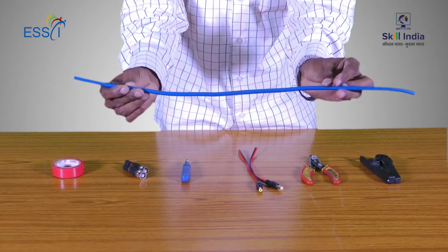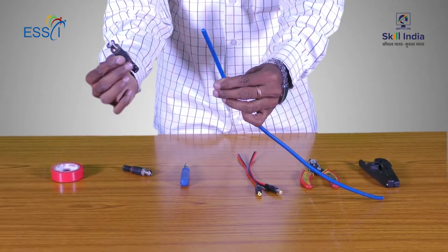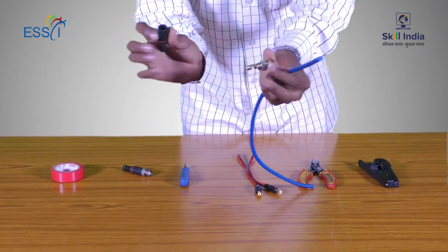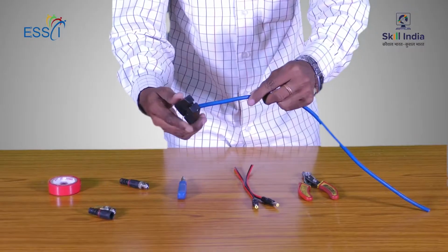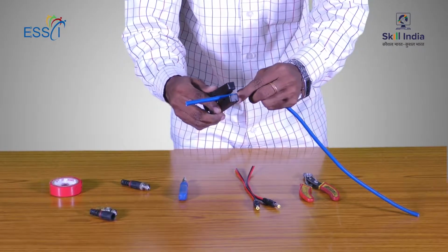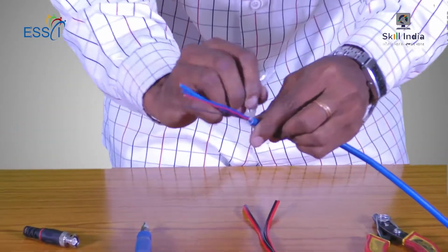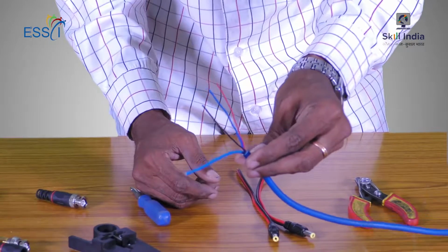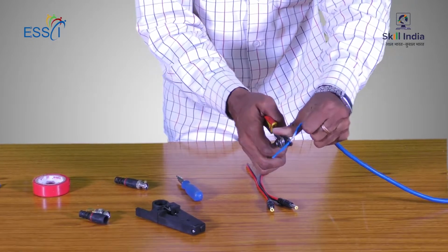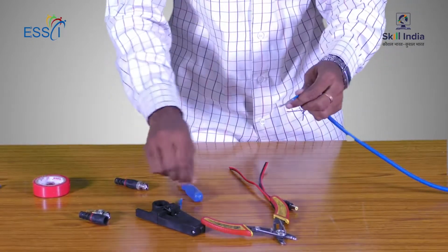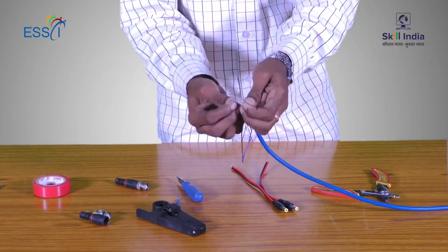This is a coaxial cable with a pair of DC supply wires. We connect the BNC at both the ends of the wire. This is a coaxial cable stripper. We peel the cable from it. We peel the ends of the wire to connect it to a BNC connector. After peeling, we observe a main cable and other 3 sub-cables. Hence this wire is known as 3+1 cable. The main cable, which is bigger in diameter, is used to insert in the BNC connector. When peeled, the main cable has a shield around it, which is removed and twisted separately.